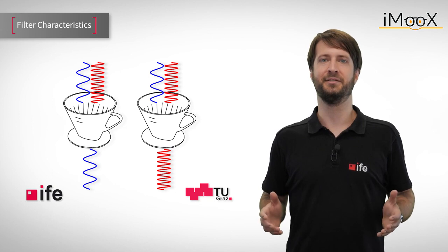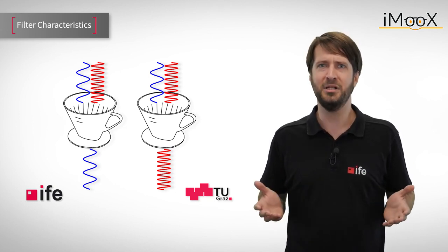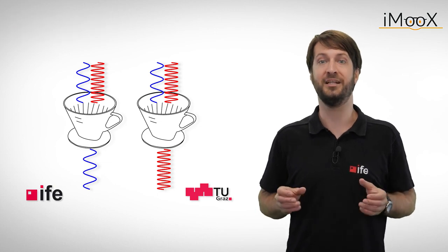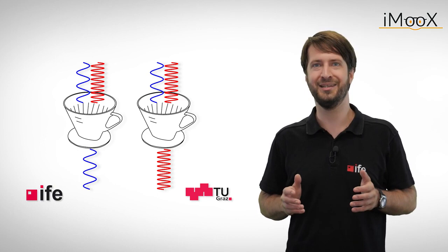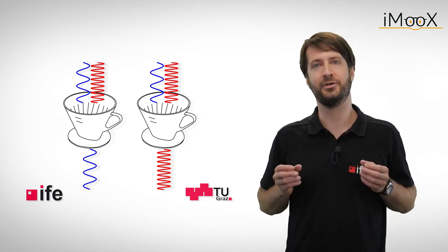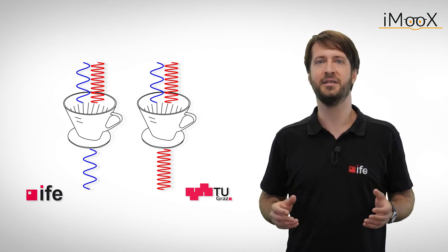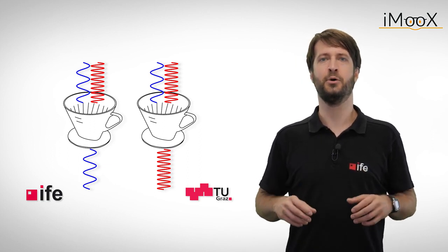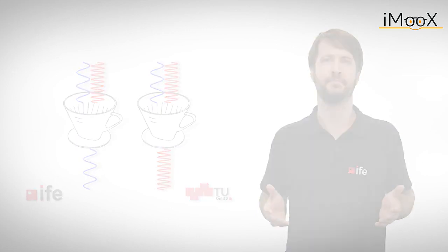But what happens here? Didn't we want our filter to dampen high frequency signals, not amplify them, much less reach values close to infinity? Of course, our theoretical approach is, like always, only a contingent truth in the real world. Real-world inductors have an intrinsic resistance, which we must add to our circuit to get to the bottom of this.